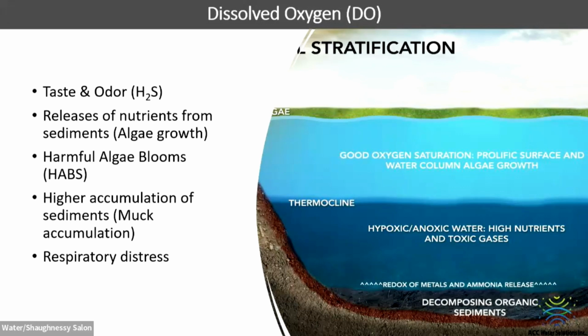So there's a case study. I'll go into more detail on this where we can actually show how it happened. But it's why, when we're talking about managing surface water, oxygen is so important, and why figuring out how to do that matters. And the science is way more in depth now than it used to be. It used to be once a month, you go out with a DO and temperature probe, you do a profile and go, oh, it's a shallow water body. Look, it's fully mixed by the wind. We don't have to worry about anything.